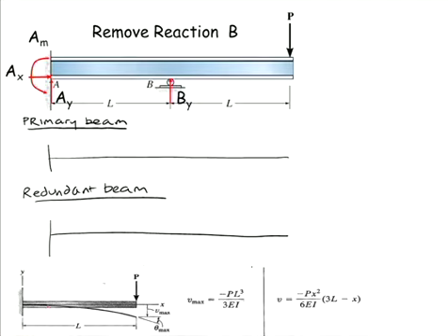Okay, our primary beam, we're going to take away our support. So this is the case where we have our load on there. Hopefully you all know it would deflect down like so. Now, where do we want the deflection? I'll call that C. At B. So it's very important you draw these, because in the tube, people go, oh, I calculated deflection there. I go, if you just drew it, you could work out where you want it. We want the deflection here.